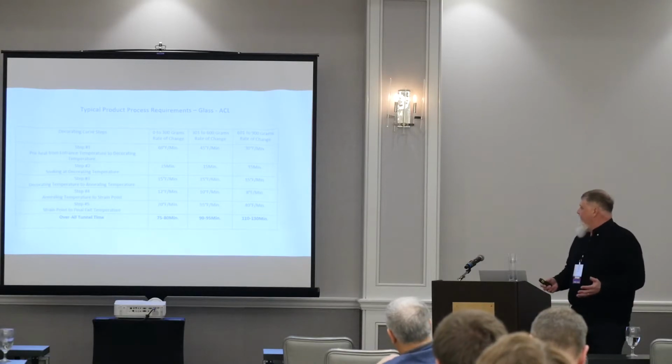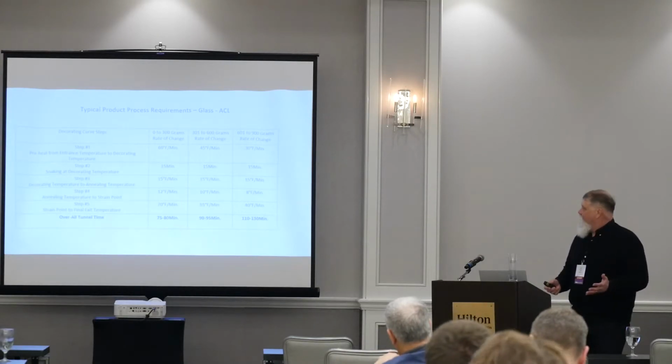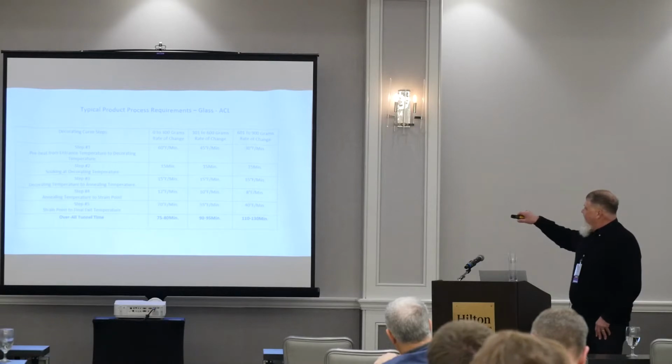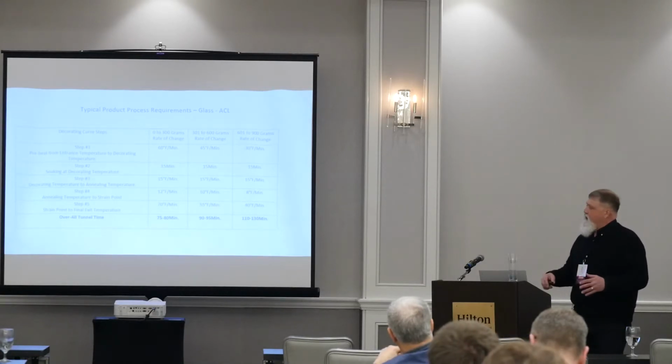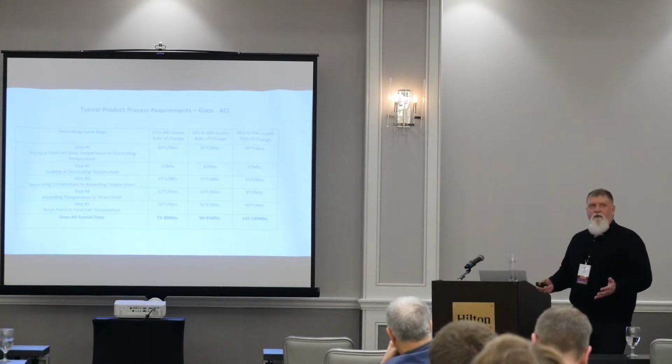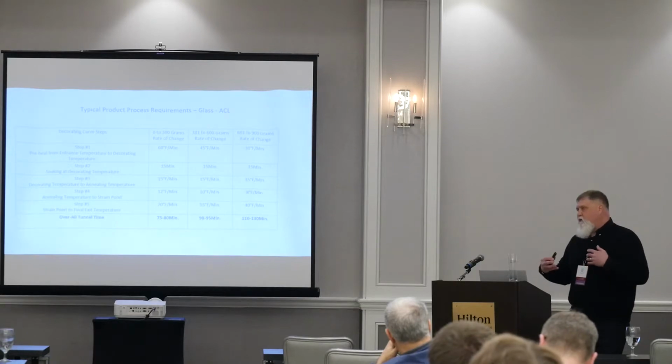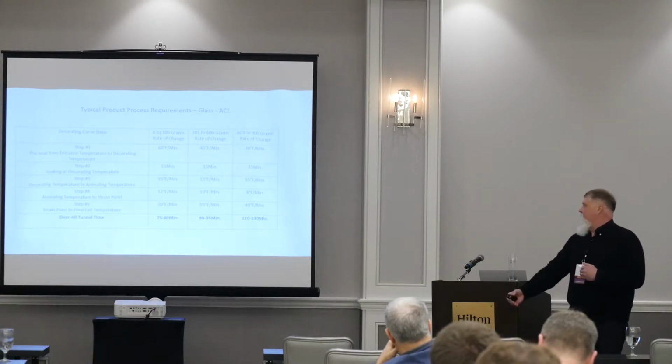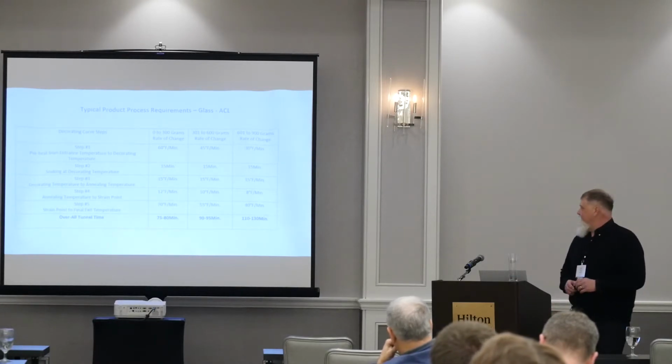Typically the annealing temperature is around 1,020 degrees, and you're going to want to maintain those cooling rates until you get an indicated air temperature in the zone. Typically I work to about 890 degrees F, because then the glass is below the strain point, and you can move to your next step, or your increased cooling rate from strain point to exit temperature.